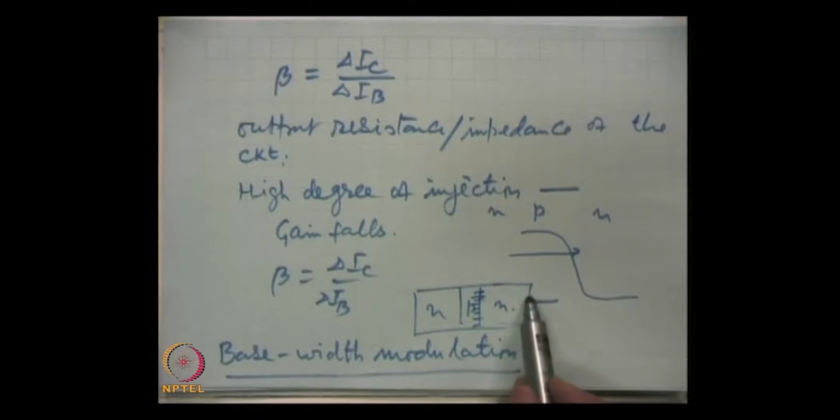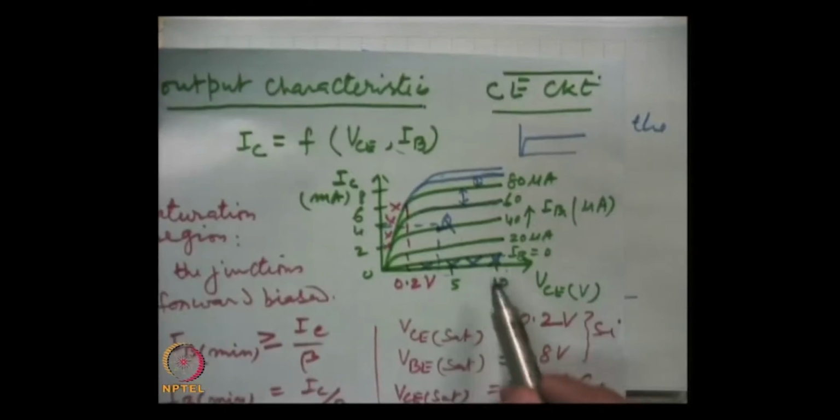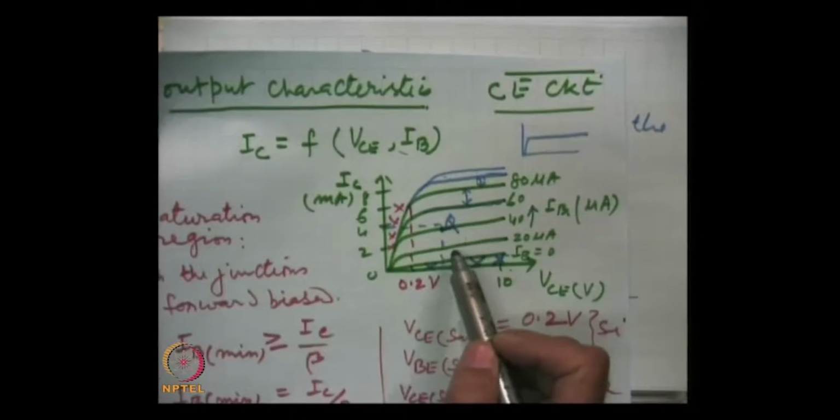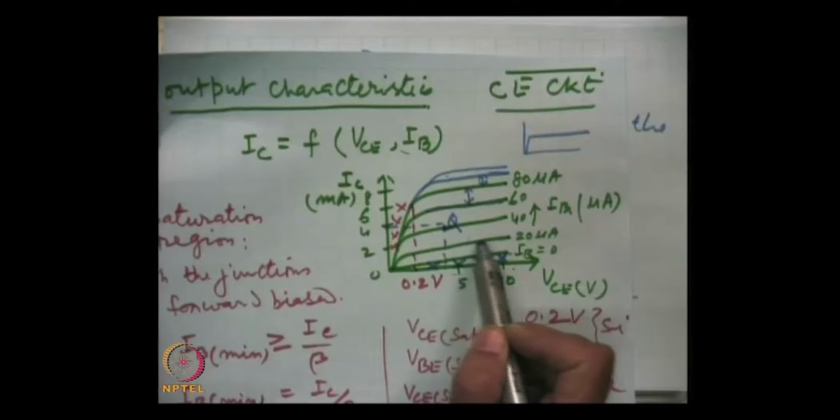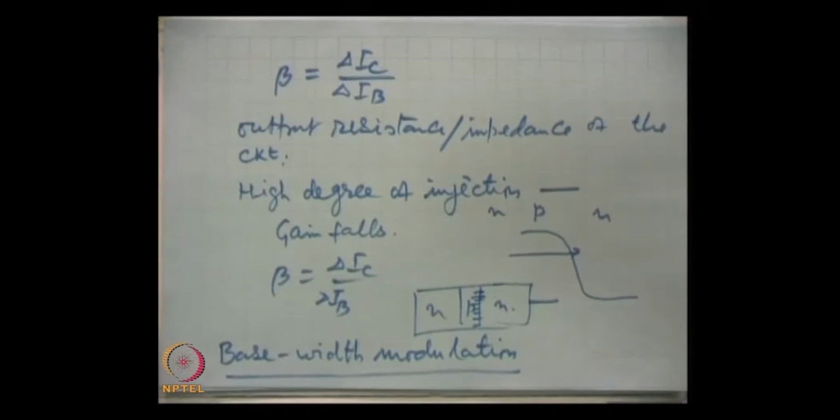With the rise of the reverse bias, the effective base width falls. So, a lesser number of charge carriers will recombine and the current will slightly rise. So, that explains these characteristics. We can get the current gain, and we can get the output impedance from the slope itself, and these are very useful characteristics. So, that covers the input and output characteristics of the transistor.